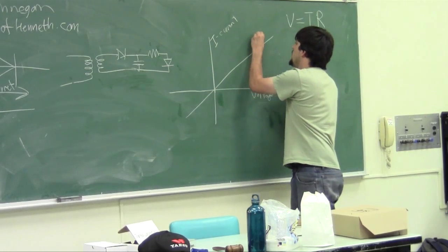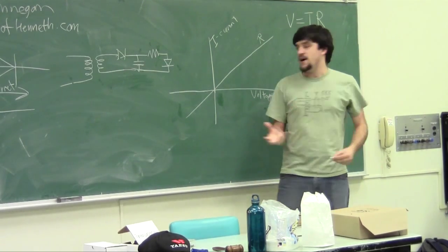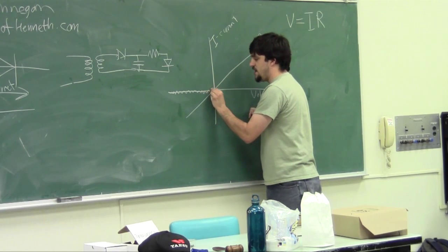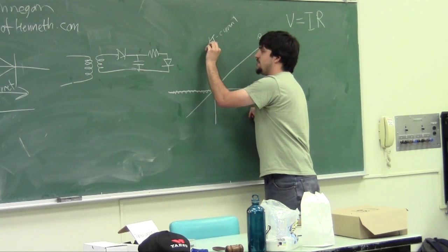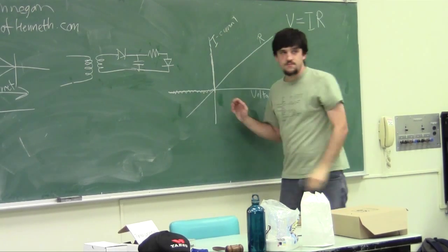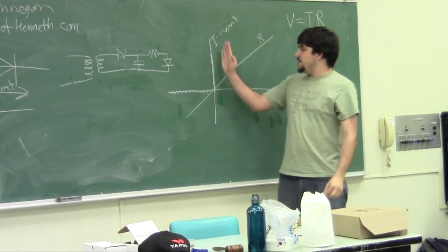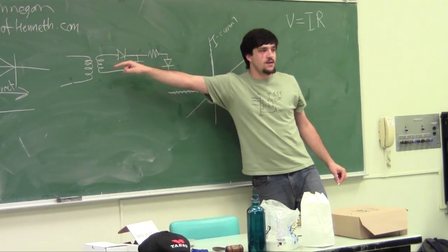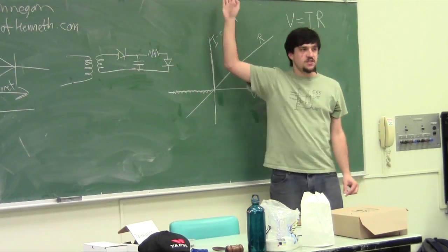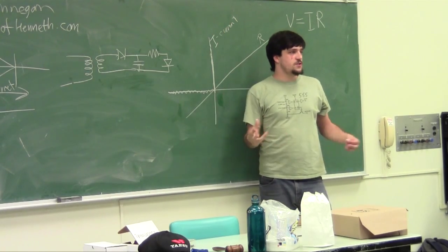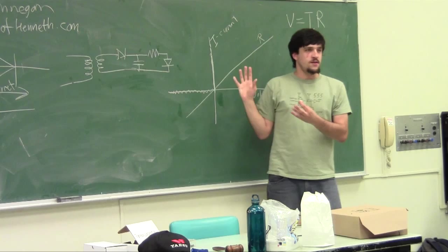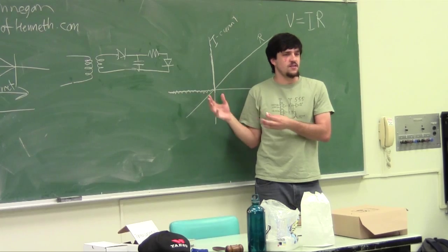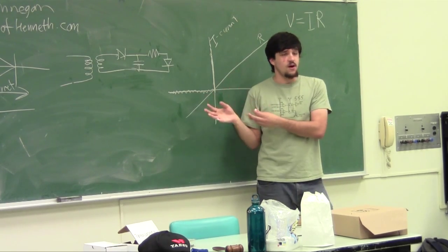So that's your resistor. Your ideal rectifier is going to have 0 current whenever the voltage is negative, and then have infinite current when it's positive, right? So that is the ideal rectifier, because anytime you have a negative voltage, it doesn't let current flow back. And anytime you have a positive voltage, it lets as much current flow through as it likes. Unfortunately, while this is very interesting in your classrooms because professors love academic, idealized scenarios like this, silicon diodes don't behave anything like this at all.